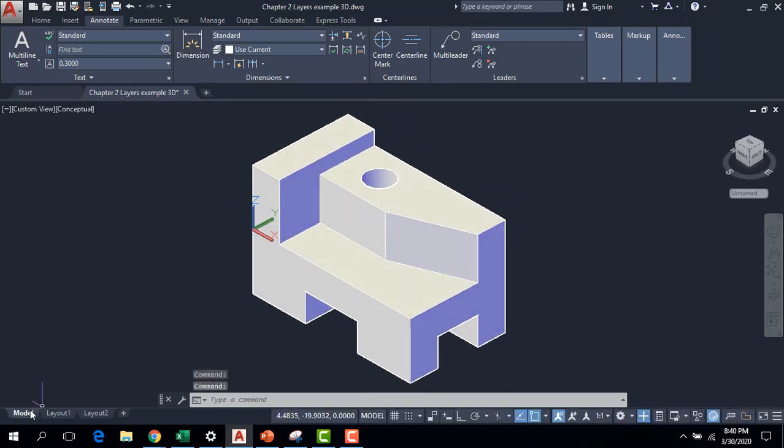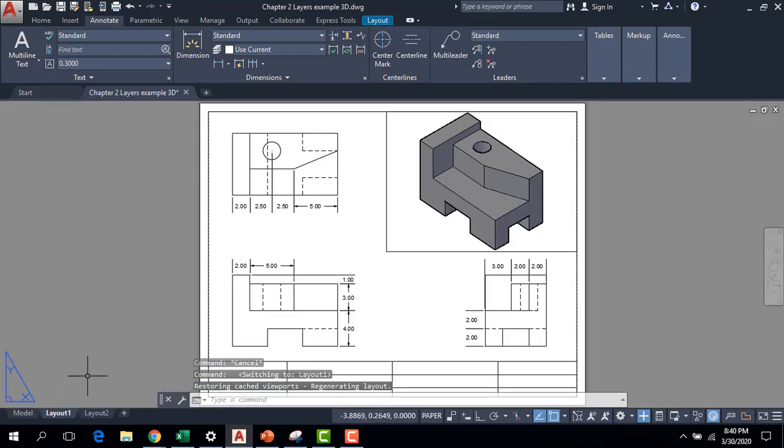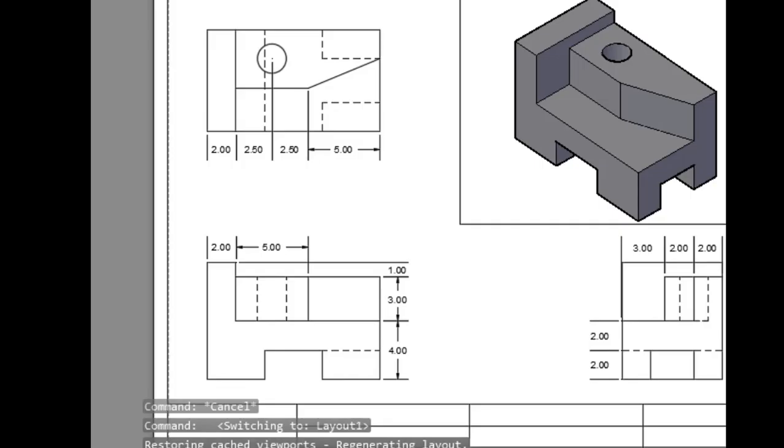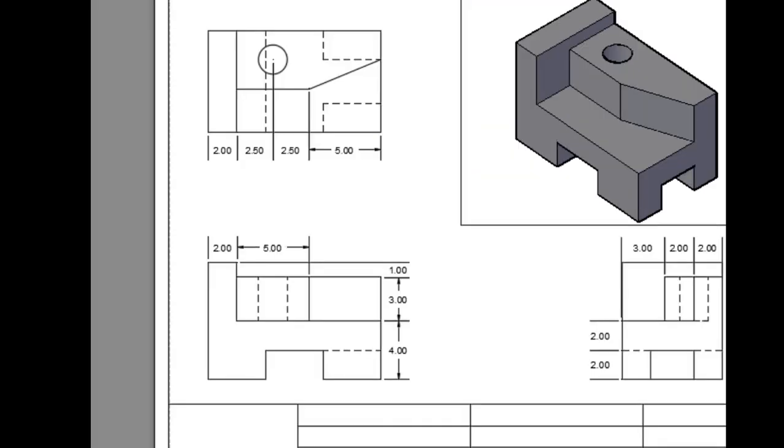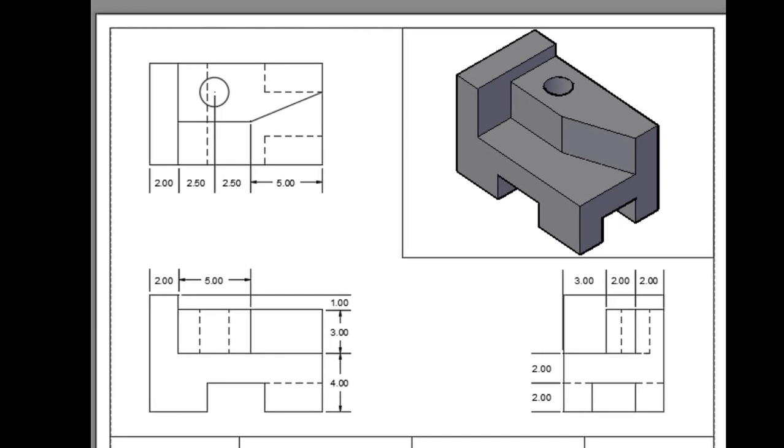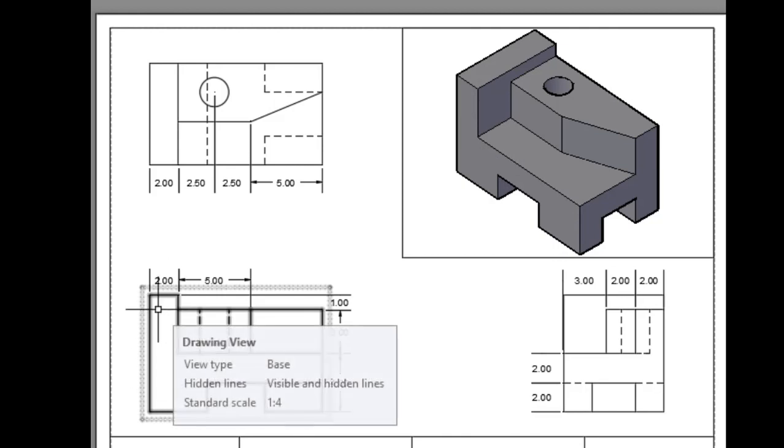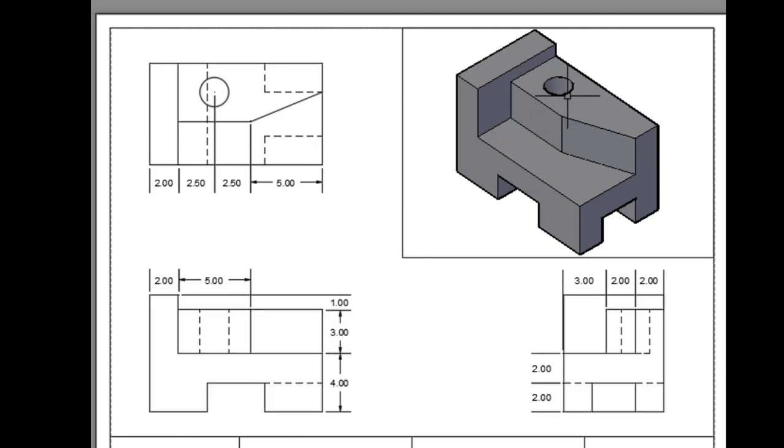The first thing to do is to really familiarize yourself with the object you're trying to draw. So if we were going to dimension this out, and you can do this on a piece of scratch paper, but the orthographic views we're after, we have this kind of long, almost a small letter H coming over here on the side. So here's one of our views. And notice the dashed lines. These are hidden lines that we'll be creating. We'll have a whole layer that's just devoted to hidden lines.